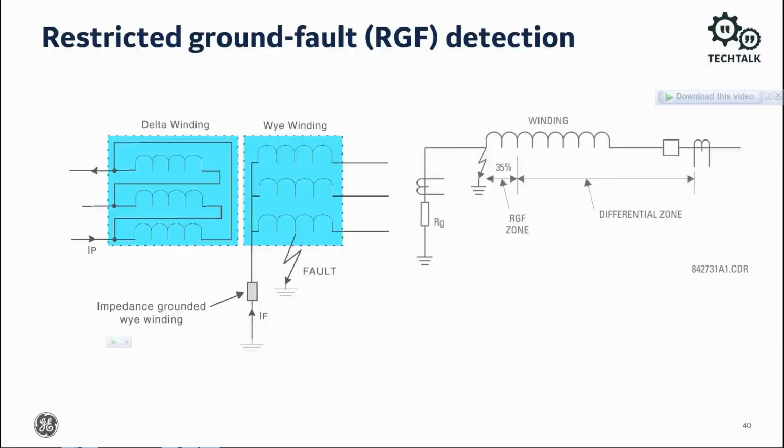An internal ground fault on an impedance-grounded or resistance-grounded Y winding produces a fault current that depends on the ground impedance and the fault position on the winding with respect to the neutral point. The resulting primary current is negligible for faults in the lower 35% of the winding because the fault voltage is not the system voltage, but rather the result of the transformation ratio between the primary windings and the percent of the shorted turns on the secondary. Therefore, the differential currents can be less than the slope threshold of the main differential element. The fault can go undetected.